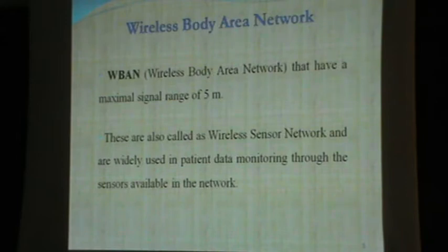And once you condition it, it cannot be transmitted as a raw signal, you need to process it. Since analog signal processing is difficult, we go for digital signal processing. If you want to process the signal using a processing element, you need to convert the conditioned analog signal into a digital signal. For that, we go for an embedded processor or a microcontroller, or even a DSP processor, depending upon the type of signal that is encountered.